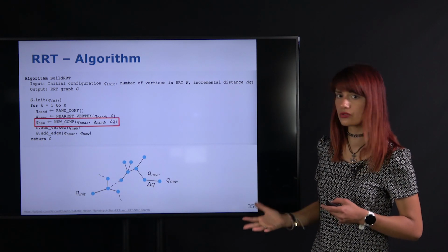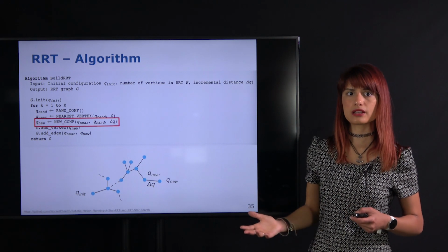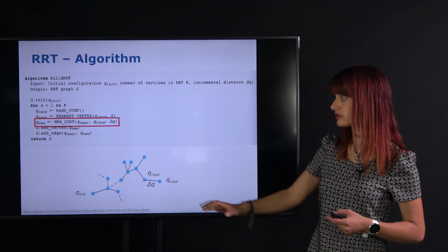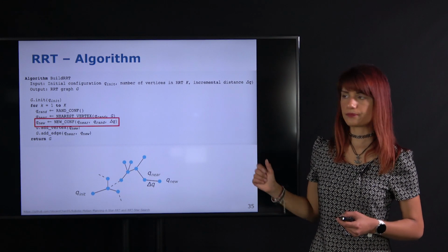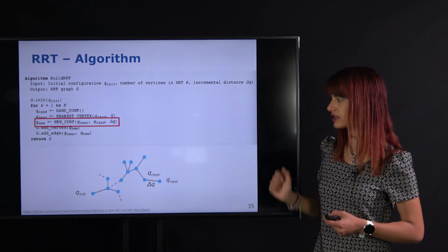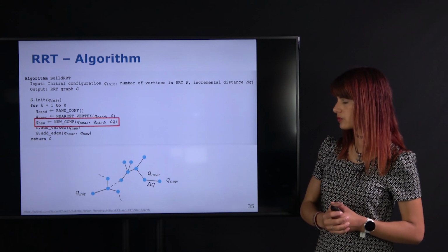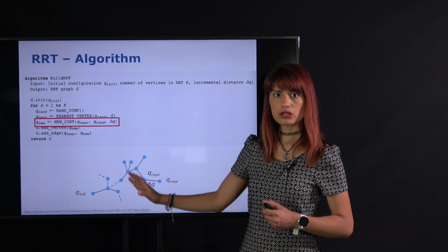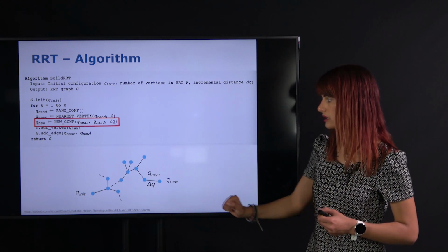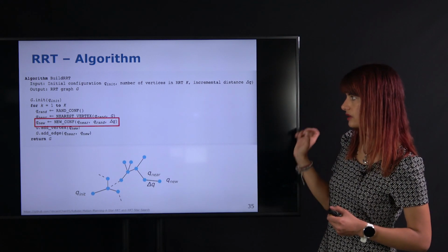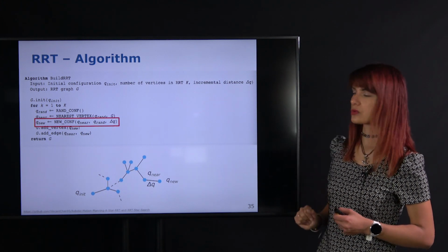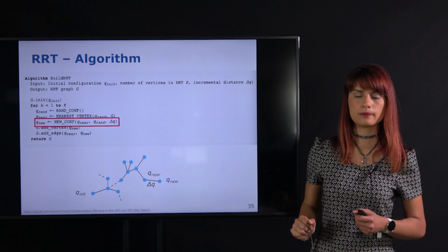And the reason why we include the step size is that otherwise our tree would attempt to connect very long distance connections and perform many checks in its search towards the goal. So we're trying to expand locally here so that we can make smaller steps rather than going the whole way towards the newly sampled node.